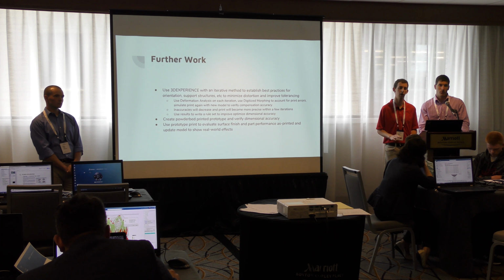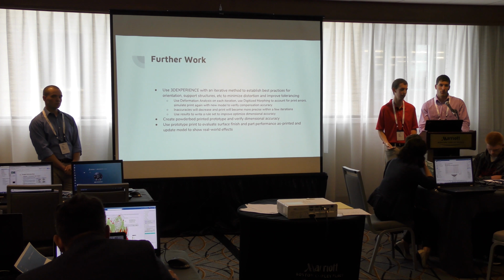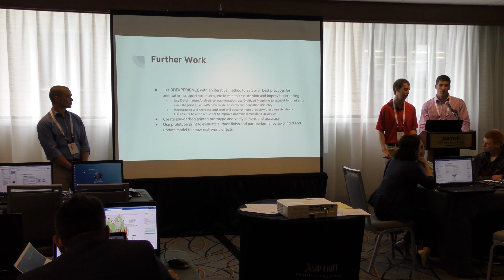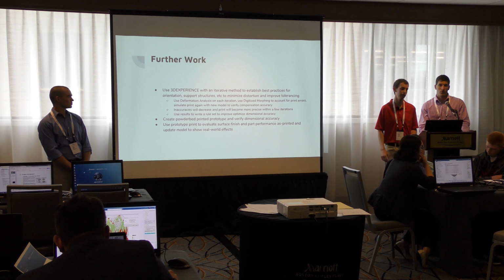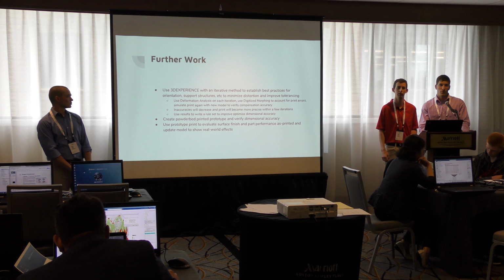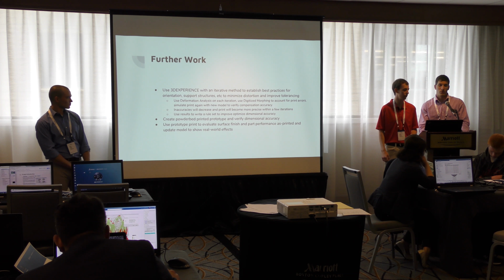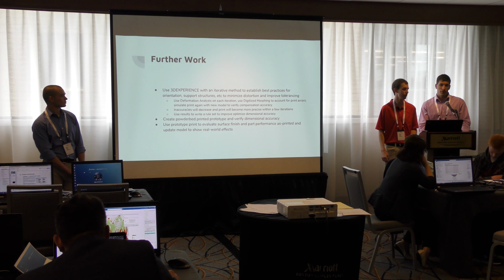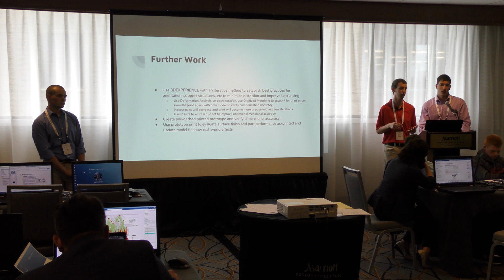and then determine whether the surface finish on the as printed parts is adequate for medical purposes, because if not, then creating a dimensionally toleranced part in the 3D manufacturing environment is, I guess, sort of irrelevant, because you'd still require post-processing to improve that surface, at which point you could change the final dimensions. But if possible, that would be the idea, is to determine that the result is as close to the original CAD model and as close to usable in the real world as possible.